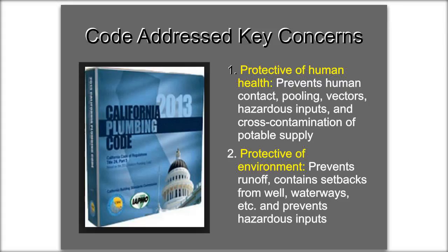And then the last really big one, there's many, many places in the code that make sure that your graywater system is not going to cross-contaminate the potable supply. So if you have a graywater system where the water is being pumped and it's pressurized, if you design your system improperly, you could potentially pump that dirty, non-potable water back into the municipal supply, which could cause health problems for your family and other people down the line. So there's many, many places that prohibit that, prevent that.